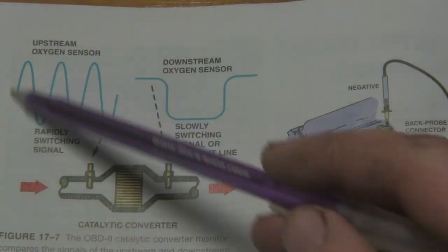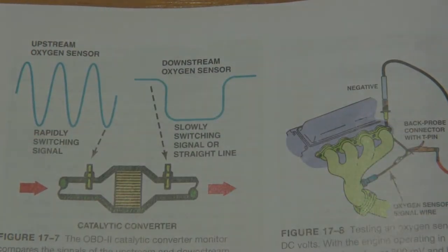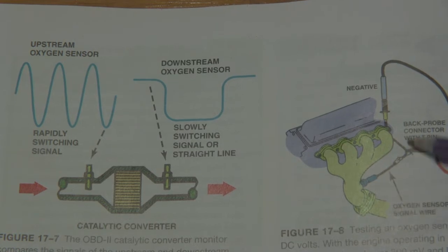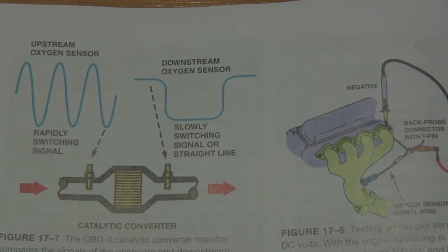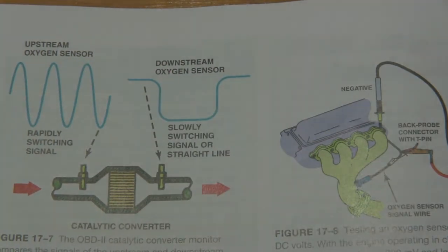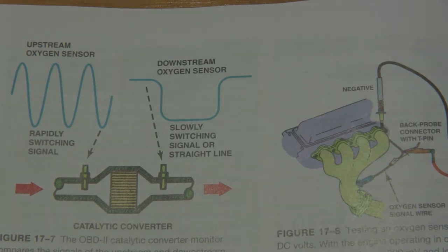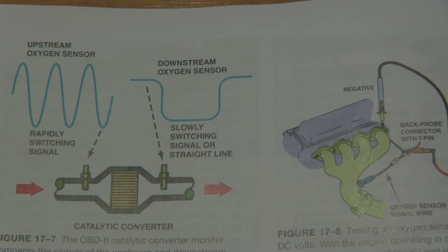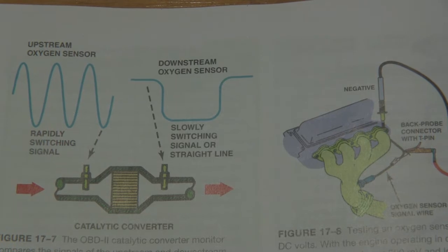This oscillation in a scan tool is cleaned up. And so what do I mean by that? If you're checking raw data, as illustrated in this picture here, if we're tied into the actual sensor, the image you see is going to be the actual raw voltage, and it's not going to look as clean as the scan tool's interpretation. So when we talk about scan tools lying to you, there are cases where scan tools will clean up an image and kind of give you a little bit of a hard time picking out an issue with a sensor, because they're trying to, I guess, filter that image.